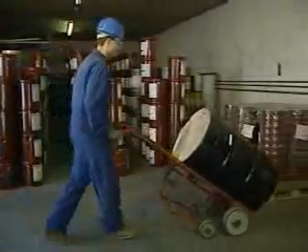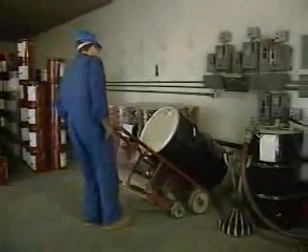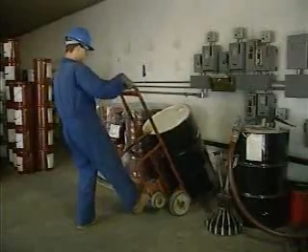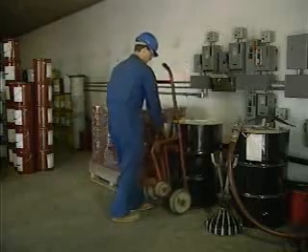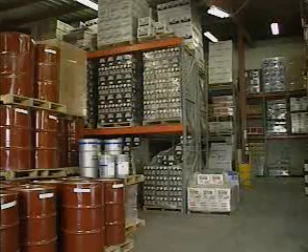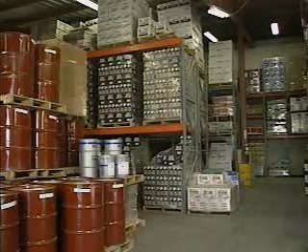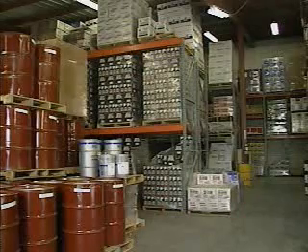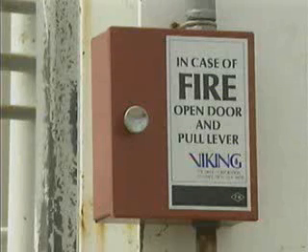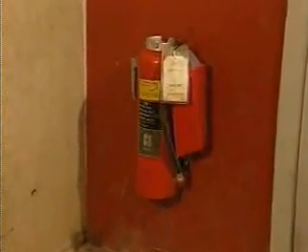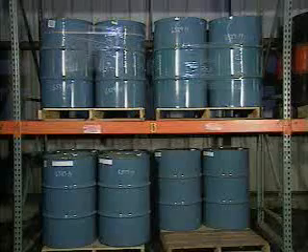When lubricants are stored indoors, weather is less of a problem than with outdoor storage. But contamination, spills, and fire are still hazards that must be dealt with. Store lubricants in a fireproof room or building that's clean, well lighted, and well ventilated. The storage area should have a fire extinguishing system that can be controlled manually as well as automatically. Also, keep an appropriate type of portable fire extinguisher in the storage room.